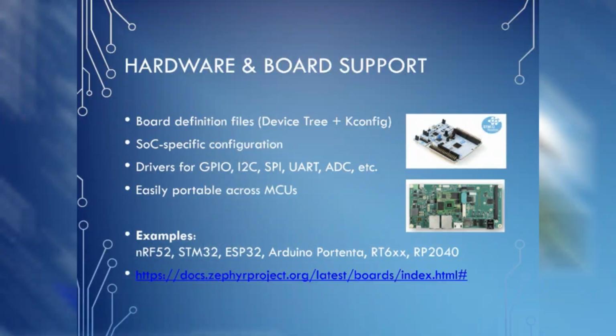This gives you flexibility depending on your timing requirements and power constraints. Hardware and board support. One of Zephyr's biggest strengths is its hardware support. Zephyr has one of the largest hardware support ecosystems. Each board is defined using a combination of device tree files and Kconfig options. This makes drivers easy to reuse and ensures consistent behavior across platforms.